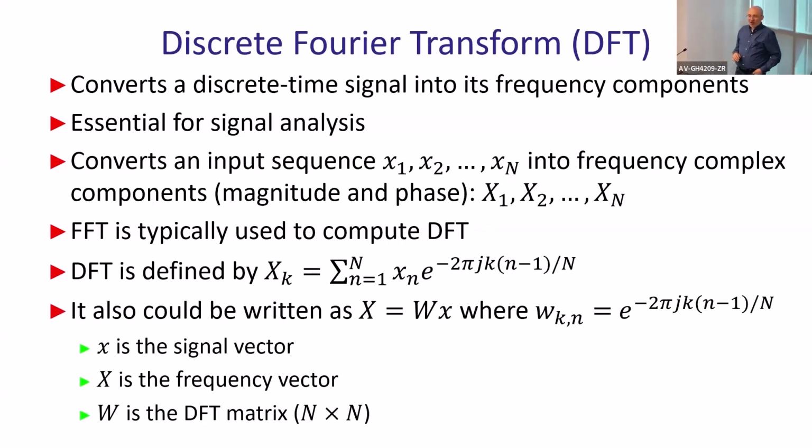But the thing is that you can write the computation of these coefficients in a much simpler way using matrices. You don't need to use that kind of approach. You can just multiply by a particular matrix, which is computed from these coefficients, okay? And this will be like a template matrix, like a lookup table type of thing, that you compute once, and you can apply it to any signal just by multiplying by that particular matrix. And this matrix will be replicating the same kind of results that FFT would do for you, okay? And FFT, by the way, is also computed with matrices. This is a different story. So the elements of that matrix, k n, will be just these exponents.